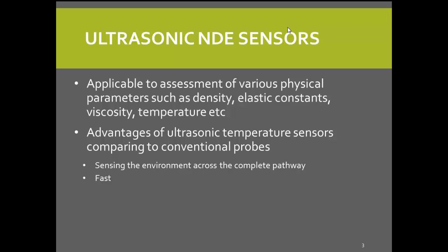And the second advantage of using ultrasonic sensors is it's fast comparing to conventional sensors. So we found that ultrasound travels 1 meter in water in only 7 milliseconds. But for conventional temperature sensors, they need between 2 to 3 seconds in order to calibrate. There should be some thermal equilibrium between the sensor itself and the medium, and